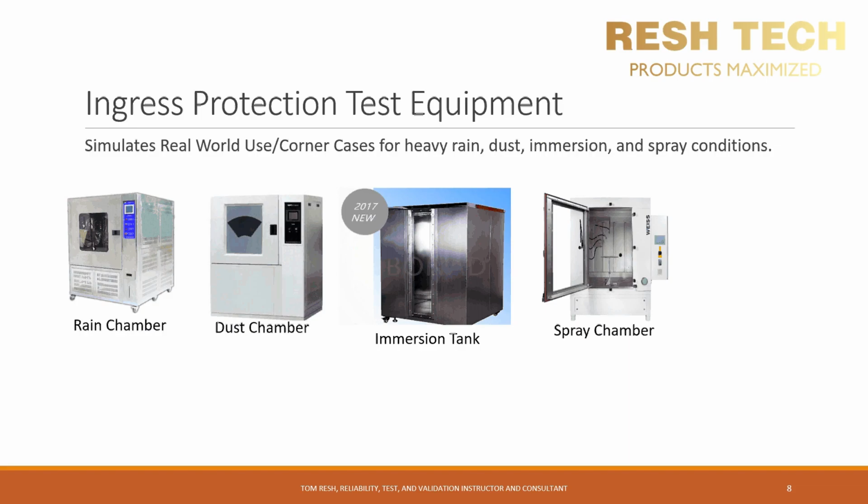Now, I'm not going to say don't buy this chamber. I mean, if you really want to have an impressive state-of-the-art test lab with equipment that nobody has ever seen before, go ahead and get this piece of equipment if money is not an option or not an issue for you. This tank in this example allows for testing to IPX7, or up to 1 meter of immersion in water. There are variations that include immersion in salt water, which can wreak all kinds of havoc on your product. So keep that in mind if you are designing a product that has the possibility of getting dunked in or splashed with salt water.